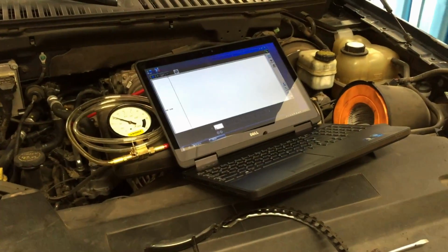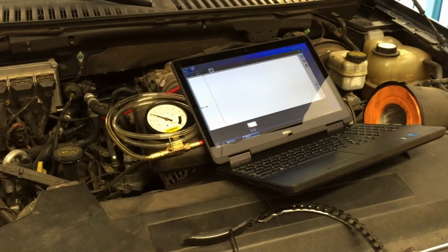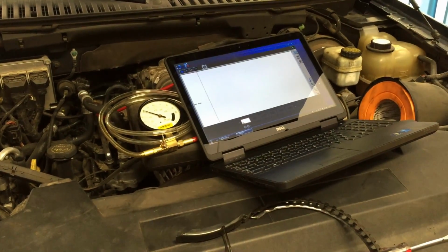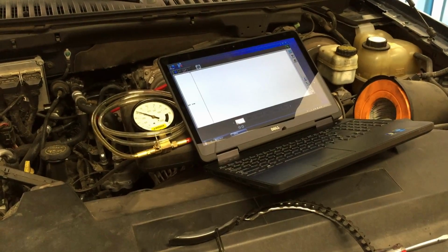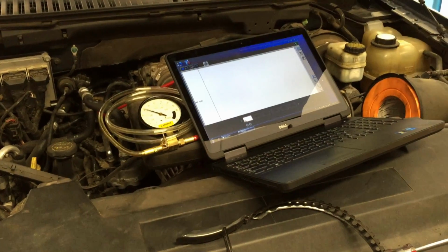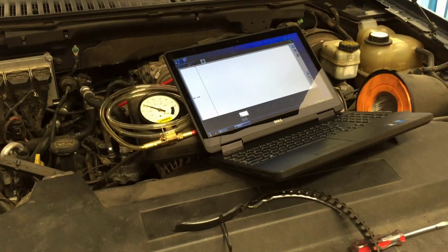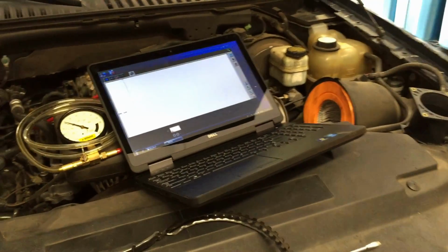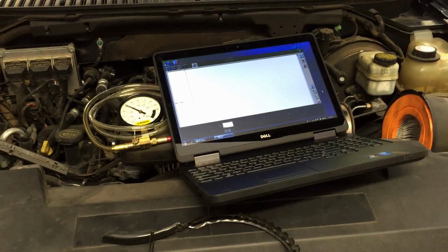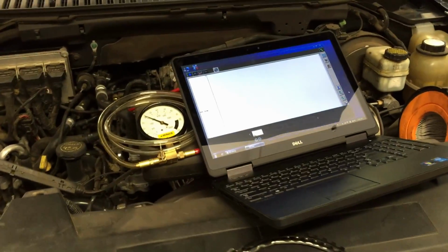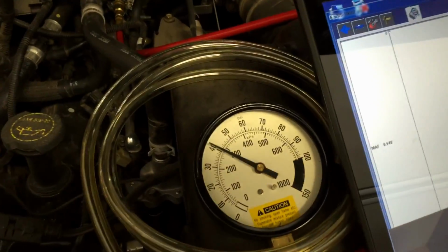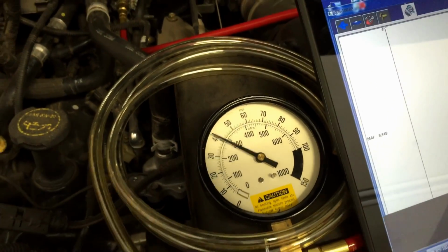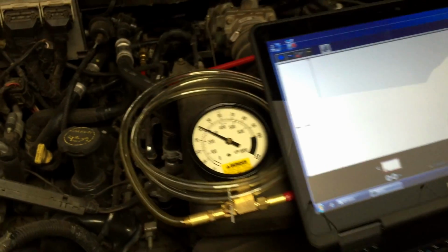Well, that's been kind of ruled out. This thing's had about 6, 7, 8 tanks of fuel through it since the last time I've been here. And fuel pressure, of course. But I did a little test on the road while I'm driving, where I kind of just gun it and see if the transmission shifts or not, and that can tell you a lot about fuel pressure. So that passed, and then you put a fuel pressure gauge on. I haven't done that yet, but that's definitely no problem so far.